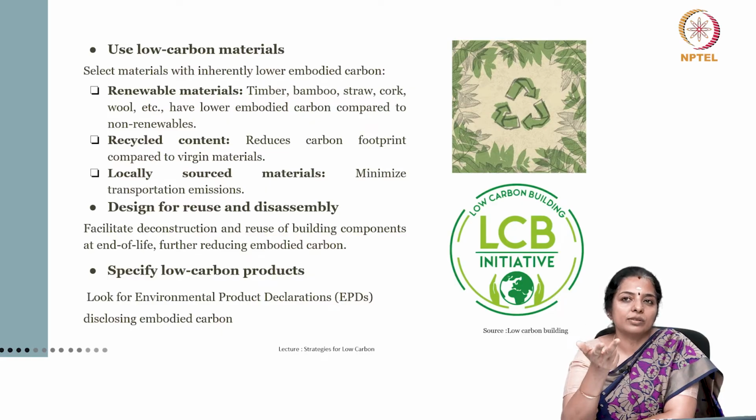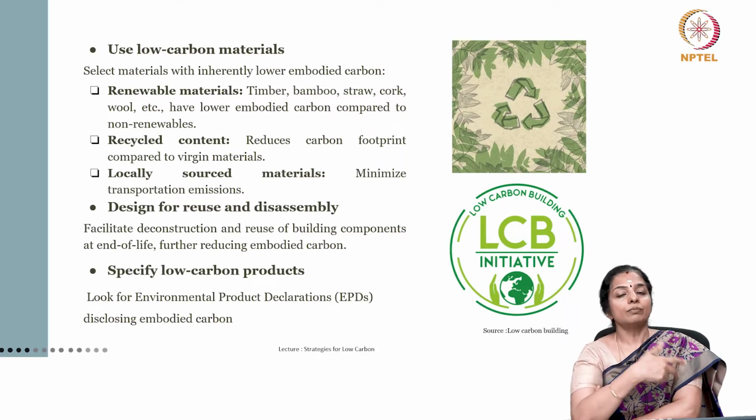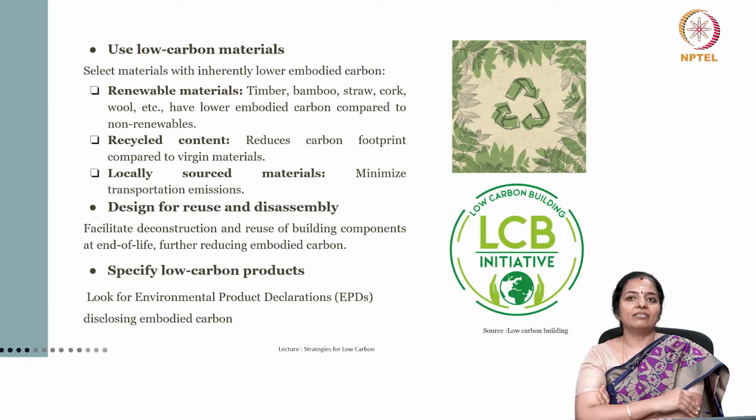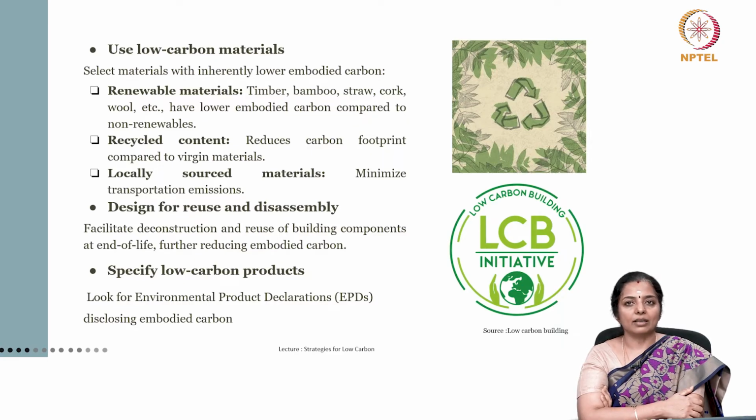Use locally sourced materials because you minimize a lot of transportation emission. Diesel is a major contributor to greenhouse gas effect. Right from its manufacture to its use on the road, it contributes a lot to the greenhouse gases, or its global warming potential is very high. So using locally sourced materials will minimize your transportation emission. For example, instead of XPS insulation, alternative insulation can be used, which will have low embodied carbon.